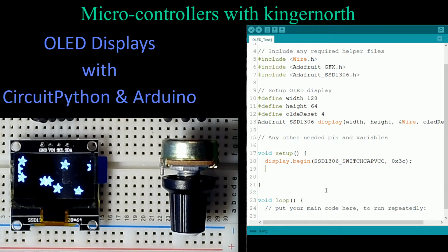So now that we've created the display, the first thing we're going to want to do is blank the display. So we just use the word display, and we hit display dot, and we're going to clear the display. And luckily the keyword for that is just clearDisplay, and just close it into the brackets. What that's going to do is turn off all the individual pixels on that board. It's going to set them all to black. In other words, turn them off.